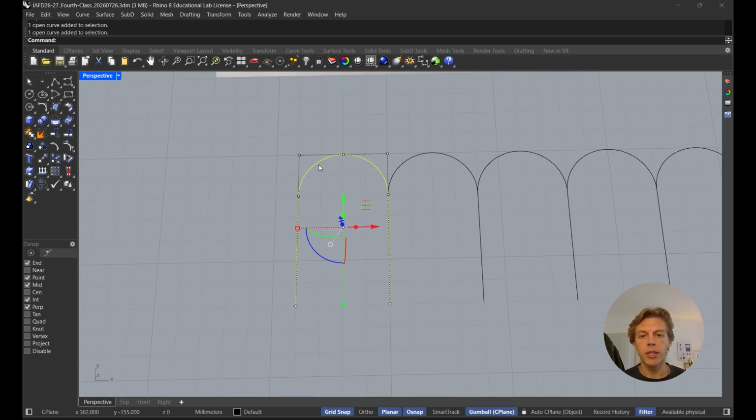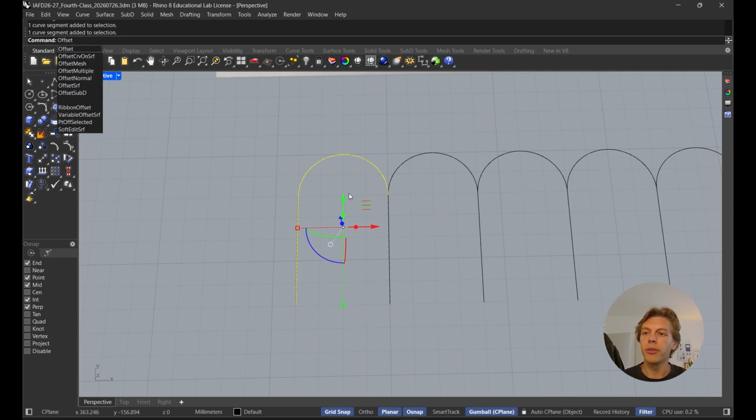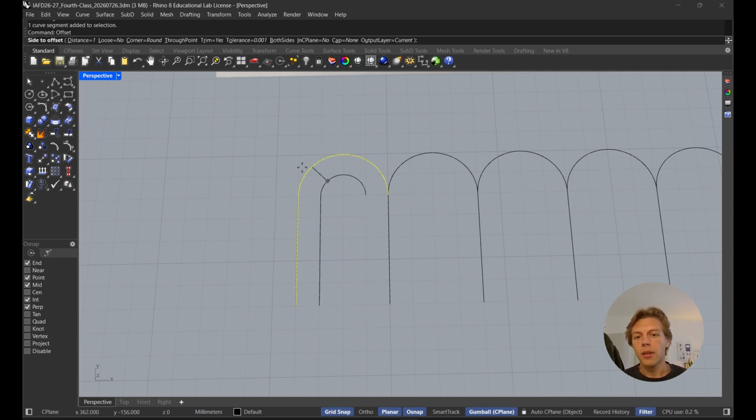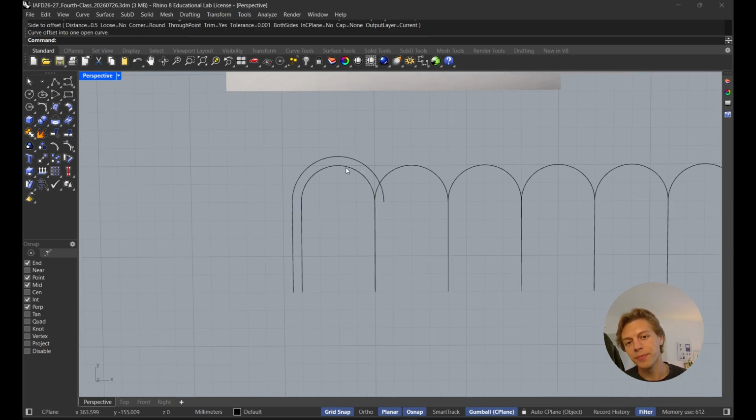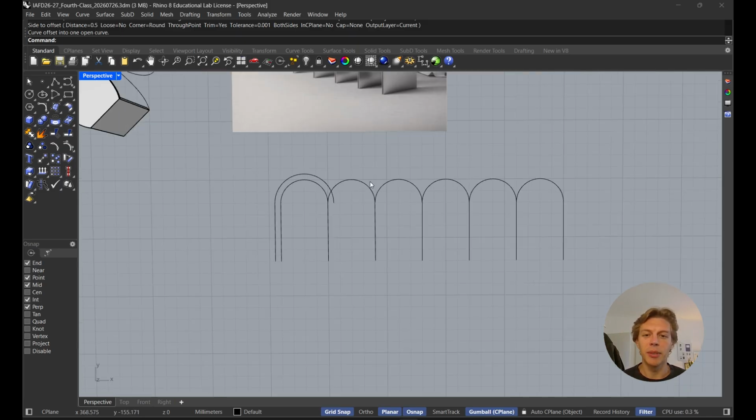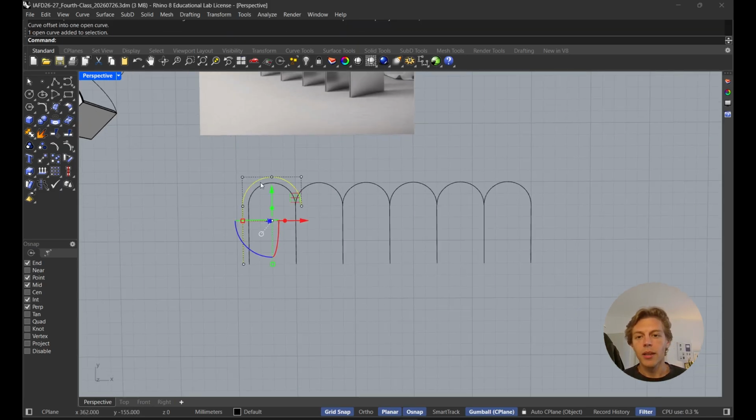And the next thing we can do is create the outside shape. So perhaps here it would be interesting to select these two shapes by holding Control Shift or Command Shift, and we can try to do a regular offset. I think 1 is too much, so let's try 0.5. That sounds okay. That looks okay as well. However, it is going inside of my shape here, but we'll fix that in a second. We of course need this on the other side as well.